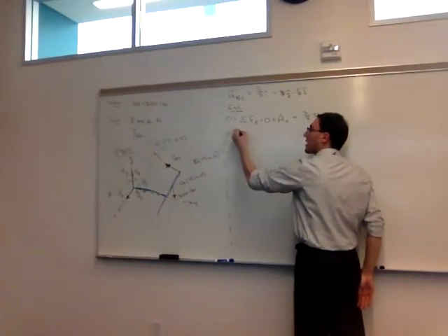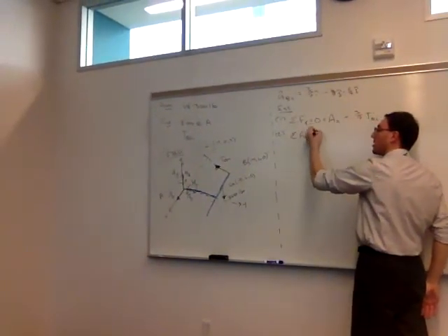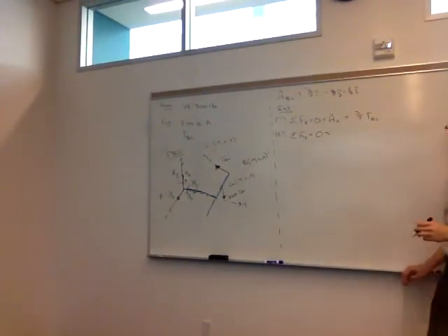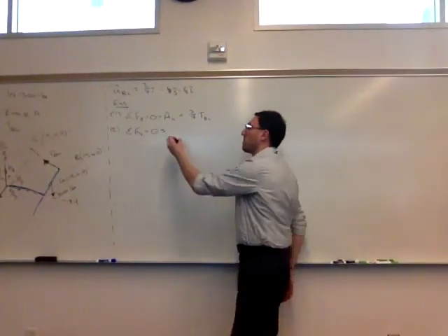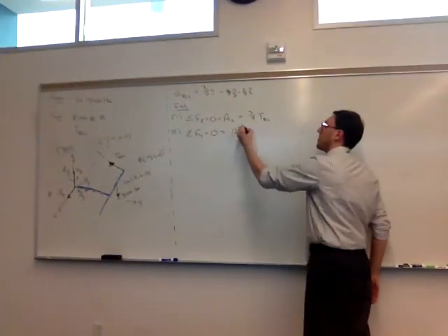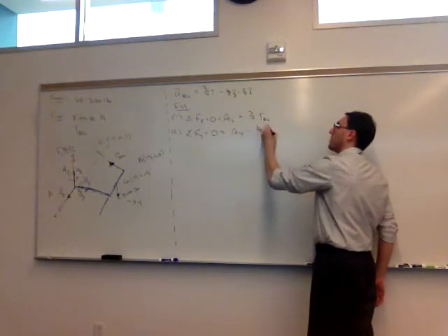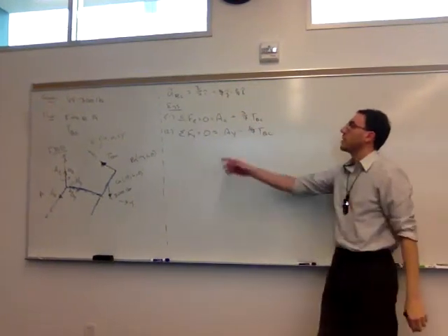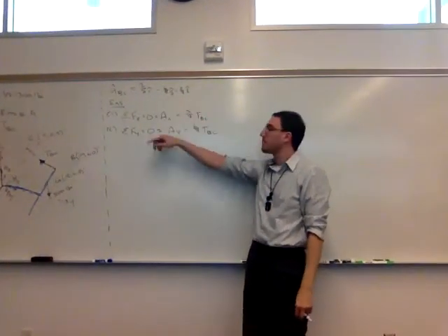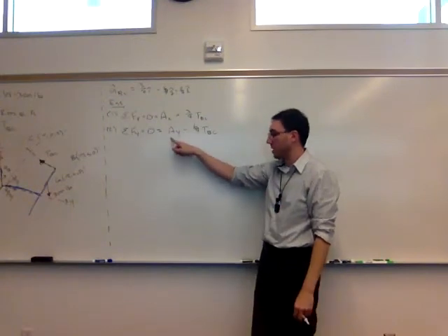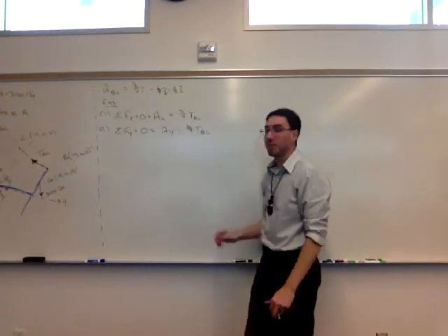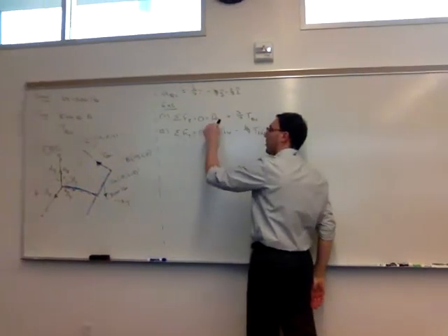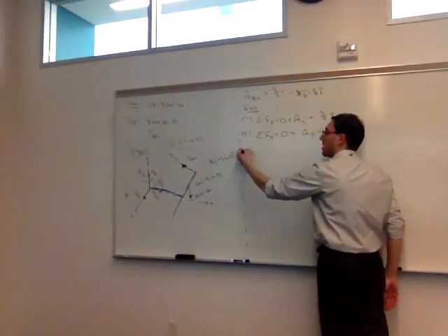And I can go to my second equation and do the same thing in the y direction. So what's my right-hand side here? Right, so the j component of TBC, all of Ay is in the y direction, and that's it. So 3 unknowns, 2 equations.